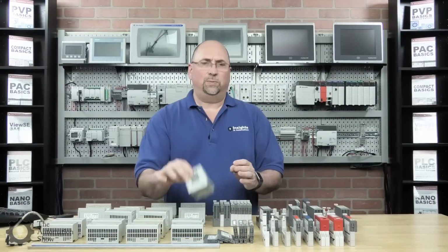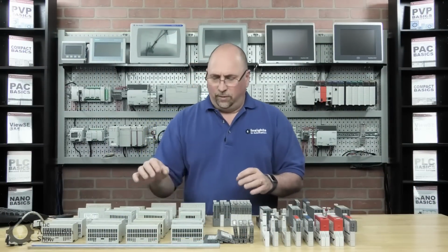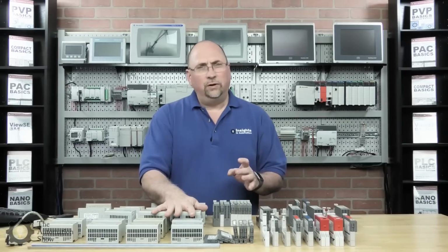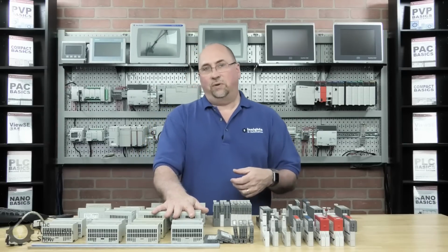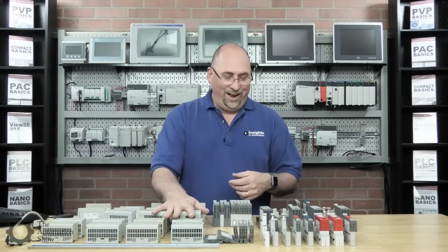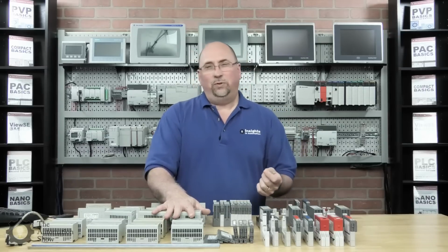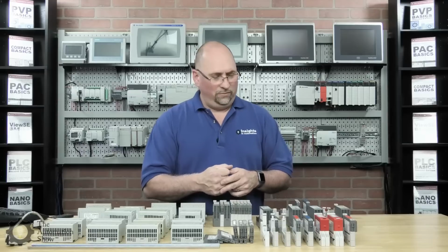Now, one thing I don't have here is remote I/O. I'd love to get my hands on one, especially the Flex-IO version. Flex-IO was very popular on remote I/O, the old remote I/O for, well, typically PLC5s and SLC 500s, typically PLC5s. It was kind of painful to do the analog because you needed block transfers, but for anybody who's done a lot of PLC5s, that's really not that difficult if you've written a lot of programs. Now, if you're troubleshooting PLC5s, that can confuse people. But on the SLC 500, that was kind of a beast for most of the SLC 500's life. So people typically stayed away from that.